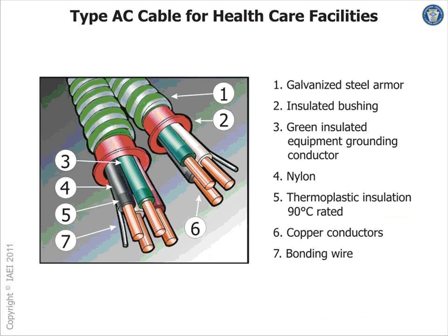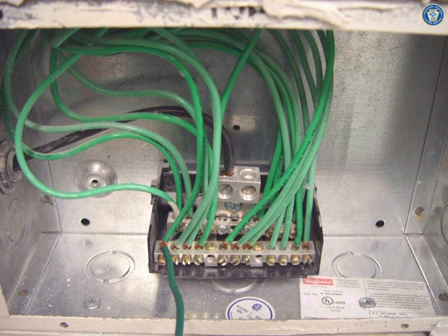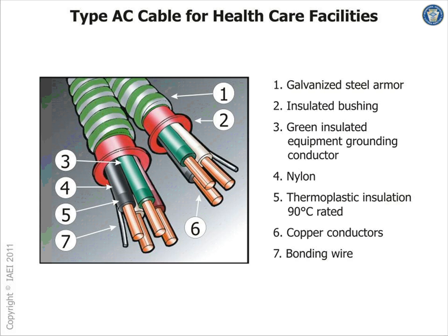So that talks to healthcare facilities. You have to have two grounds, one clean, one dirty, except you have to tie them together at the end, right? At the service. It's not an isolated ground, it's an insulated ground. You don't have to use an isolated ground.